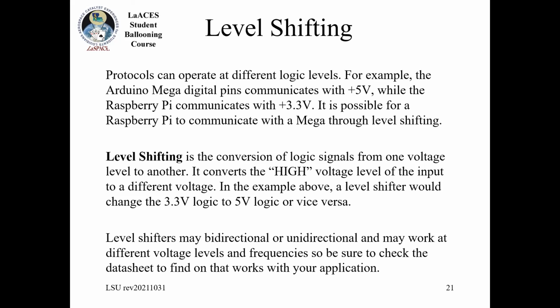Usually with your devices the low level is all going to be on a 0 scale, except for the really only common version, which is what's called RS-232, which is very old pre-USB serial ports, but is still commonly used. And that's one of those protocols that had a positive 12 volt and negative 12 volt signal for the high and low values.